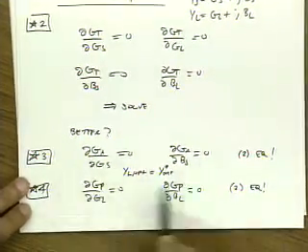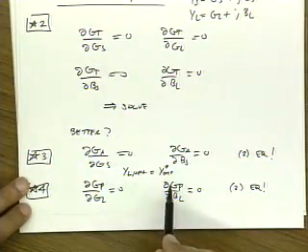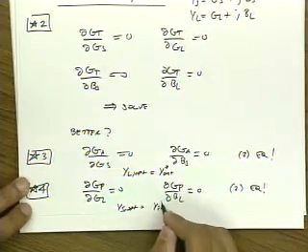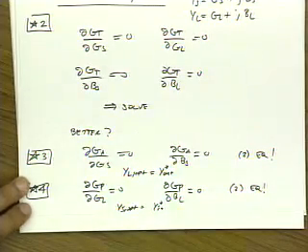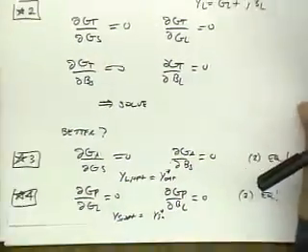So even though this only gives us the optimum source, with one line of algebra we can find the optimum load as well. And here, YS opt we can find by doing the same thing. Okay? Any questions about that? Does that make sense? Good. All right. So now we have a nice recipe for doing a simultaneous biconjugate match.